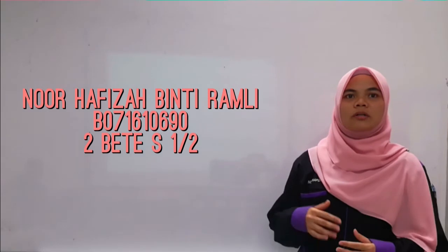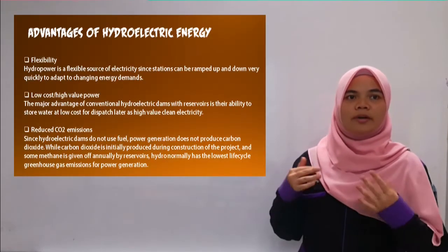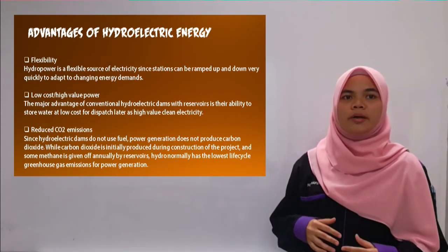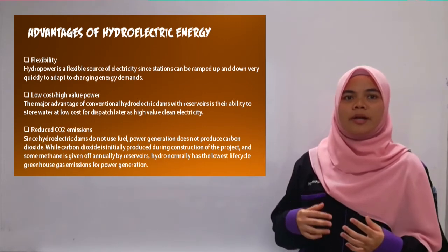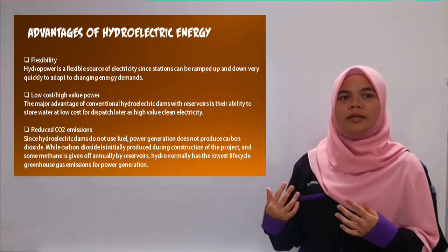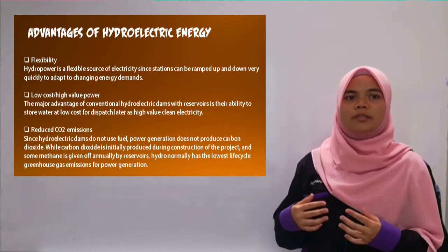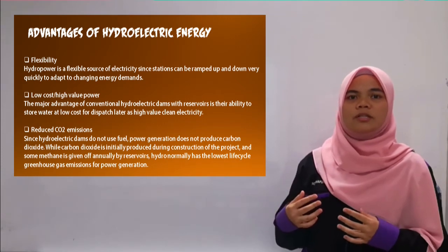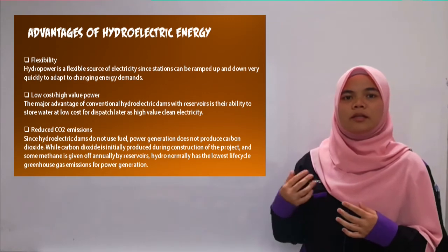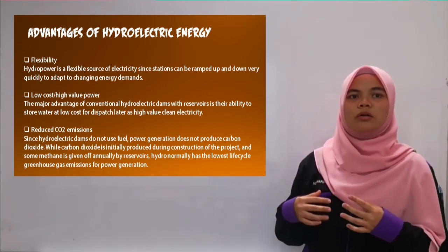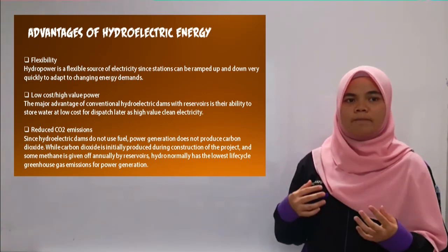I'm going to talk about the advantages and disadvantages of hydroelectric energy. For advantages: flexibility. Hydropower is a flexible source of electricity since stations can be ramped up and down very quickly to adapt to changing energy demand. Low cost, high value power. The major advantage of a conventional hydroelectric dam with a reservoir is the ability to store water at low cost for dispatch later as high-value clean electricity.